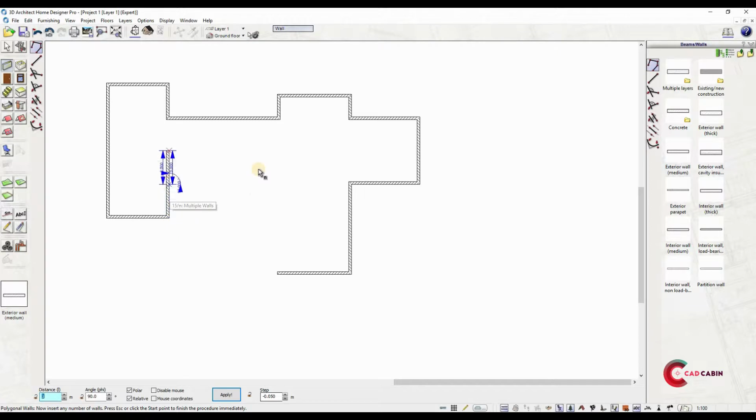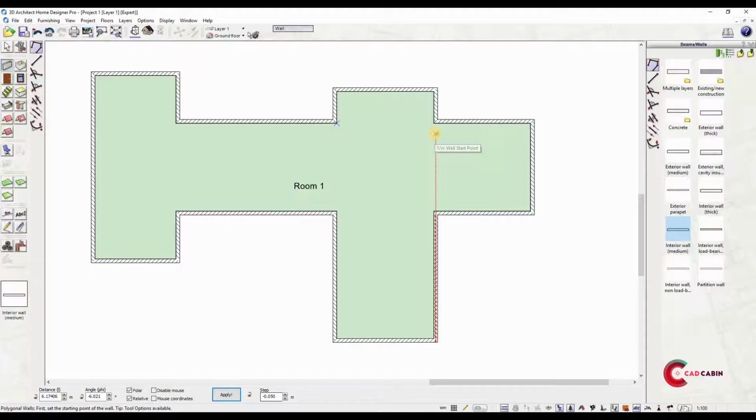To close the walls, just make sure your end point meets the starting point of the walls. After creating a large room, next, draw the interior walls. You can add your bedrooms, bathroom or any room according to your desired size. Just click on the wall starting point, drag and click to end the wall. After exterior walls, you can draw the interior walls. Using polygonal input, click on a starting interior point, enter the dimensions and continue on to the next adjacent wall. Do this until you have created another room.